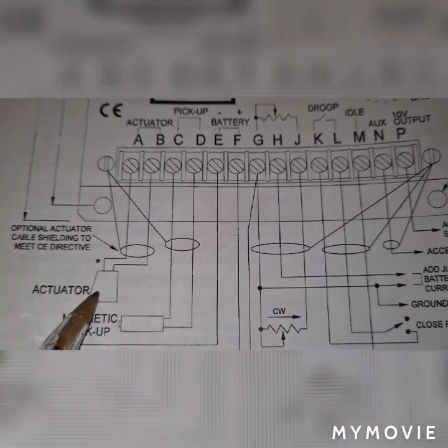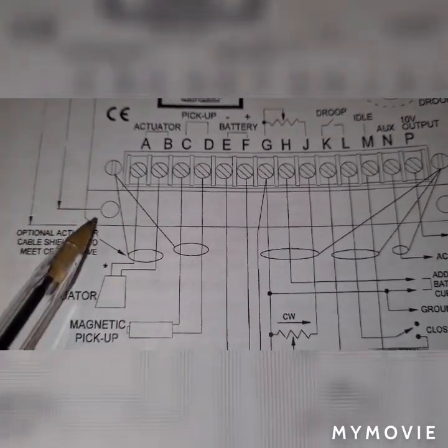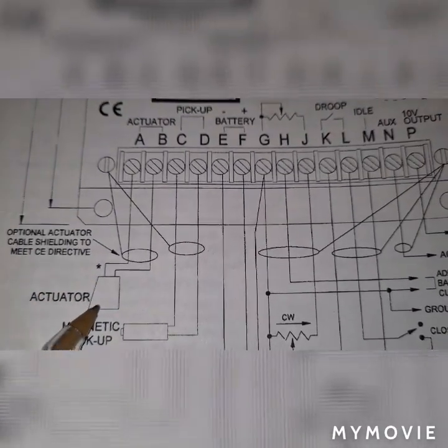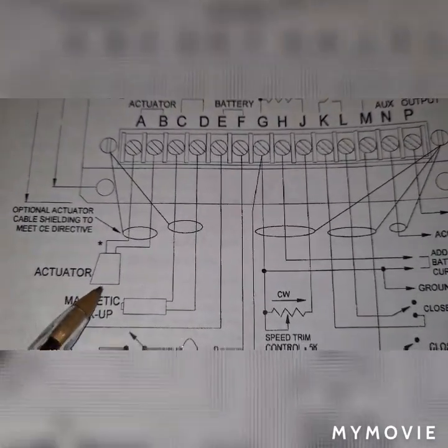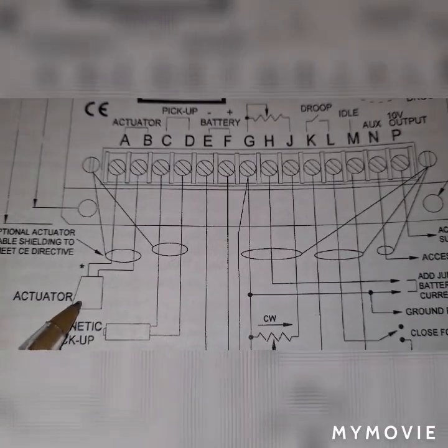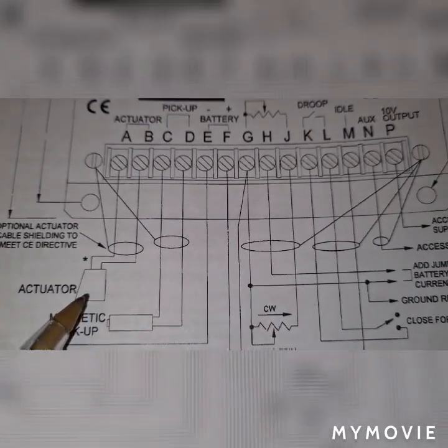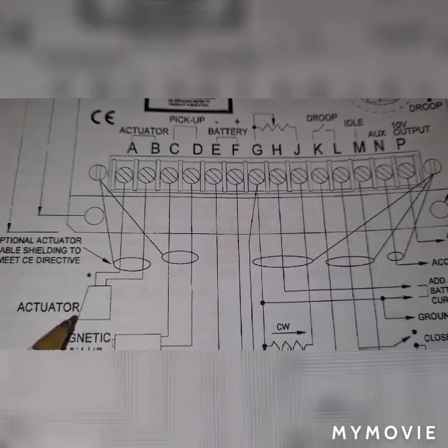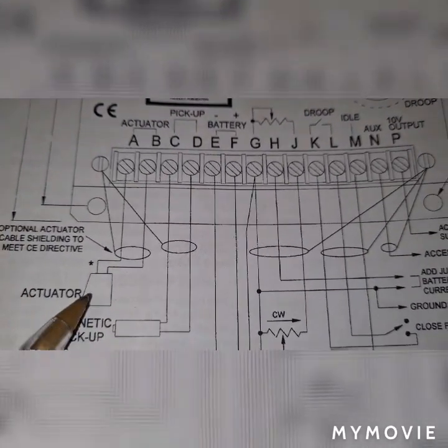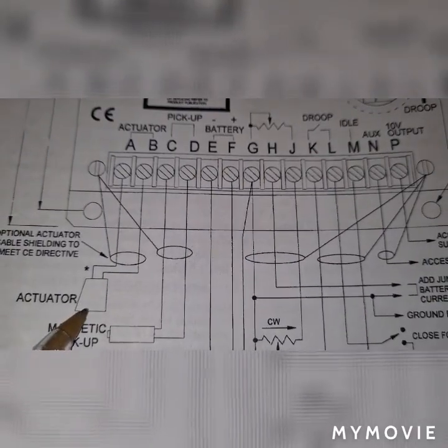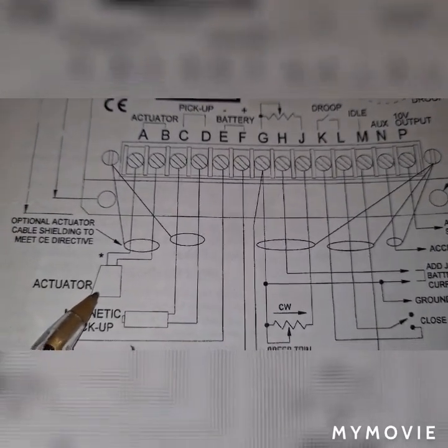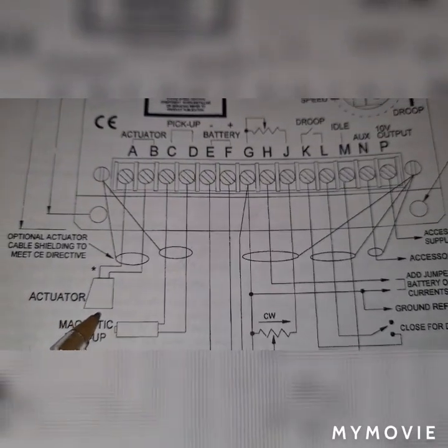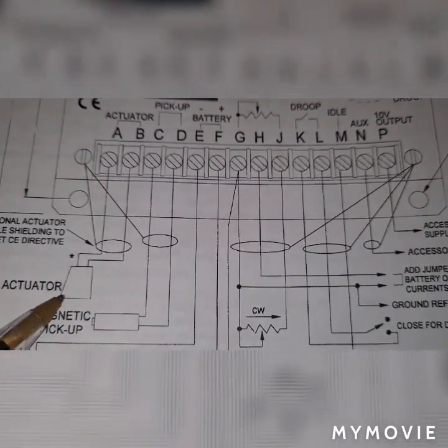The actuator will inject more fuel so the engine will rotate at constant speed. With more load, it commands to inject more fuel to your engine. By principle, more load produces more torque that your engine must compensate. So the actuator will give more fuel to increase the force that rotates the engine of your alternator at constant speed.